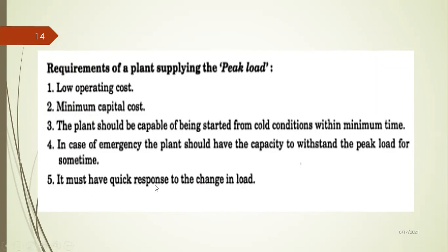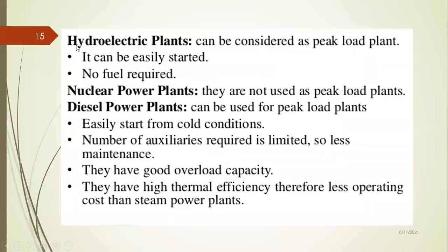And it must have quick response to the change in load. So it can handle the change in load. Whenever the load is increasing or decreasing, the switching on and off is quick in these types of plants. In case of hydroelectric power plants, it can be considered as a peak load plant. It can be easily started and no fuel is required.